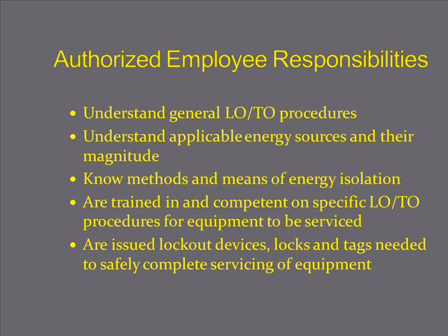As an authorized employee to use lockout-tagout, you have several serious responsibilities. You need to understand general lockout-tagout procedures, understand applicable energy sources and their magnitude, know methods and means of energy isolation. You must be trained in and competent on specific lockout-tagout procedures for equipment to be serviced, and you're going to be issued lockout devices, locks, and tags needed to safely complete servicing of equipment and/or circuits.